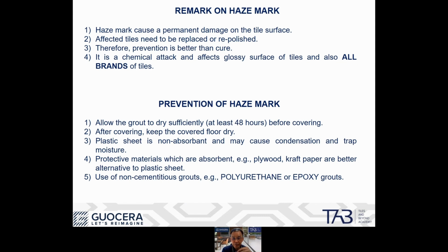Alternatively, because I talked about the calcium oxide in the cementitious material, you can eliminate either the water or the calcium oxide. So the alternative would be to use an alternative grout, or alternative material in the grout. This grout is basically polyurethane or epoxy grout.